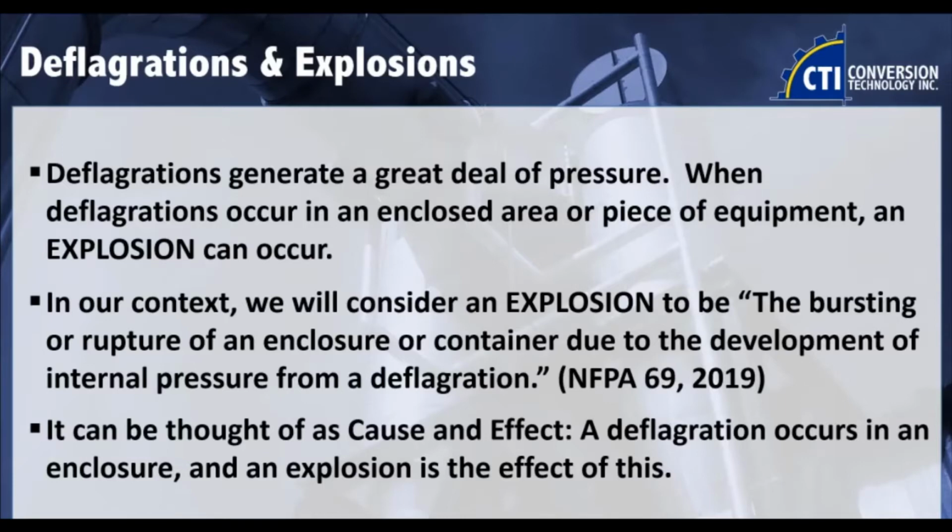So if a deflagration occurs in a bucket elevator, but that bucket elevator is equipped with appropriate deflagration relief panels, or explosion panels, or rupture panels, however you want to refer to them, and all those panels blow and it vents out, but the bucket elevator itself stays intact, then you can say that a deflagration occurred, but it didn't explode, didn't blow up the whole casing. And that's actually a case study I'm working on currently, so I can answer more questions on that. So between deflagration and explosion is pretty much a cause and effect. A deflagration occurs, causes an explosion.